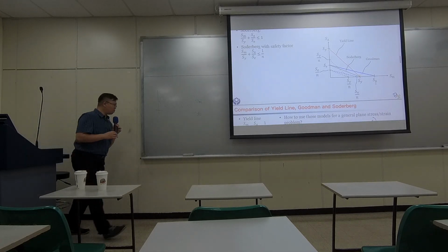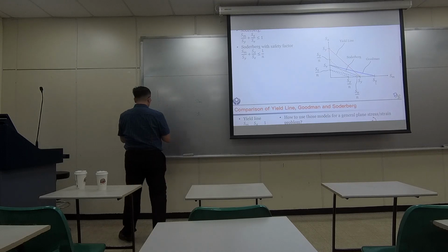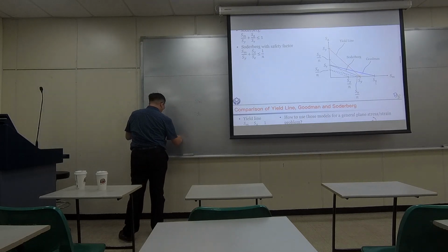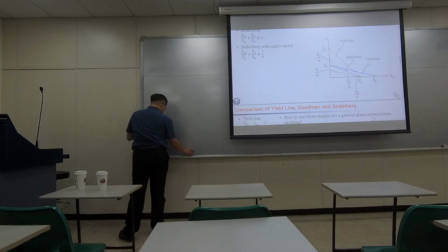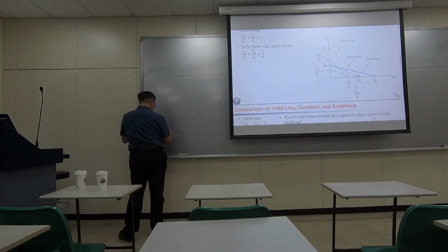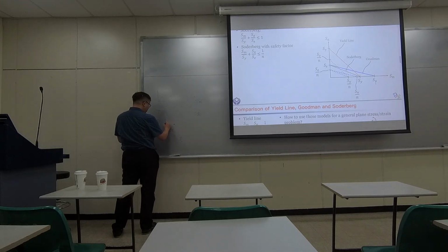Because think about how metal breaks. This is stress, here is strain. So in the linear part, this is your Young's modulus, right? So here's your yielding strength. After yielding strength, it starts to nonlinearly deform, and then sometimes it breaks right here. So here is your ultimate tensile strength.